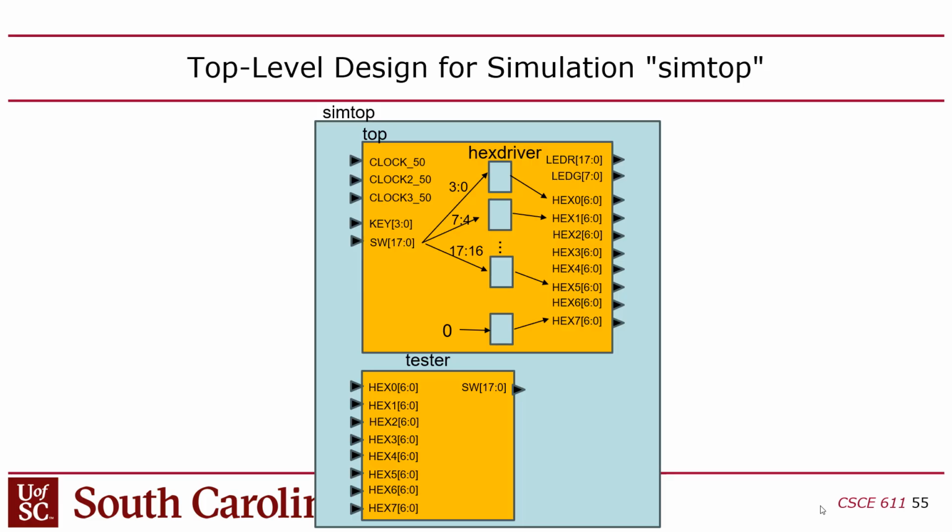There are some things you can put in Verilog that make it non-synthesizable, like putting delays in, say wait for 5 units of time. You can't synthesize that, right? There's certain data types that can't be synthesized, so if you want synthesizable code, you have to declare everything as a logic, right?